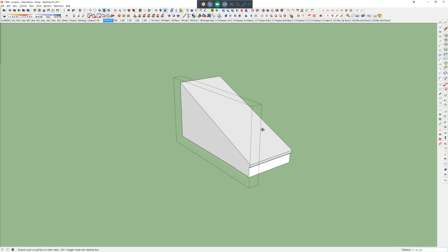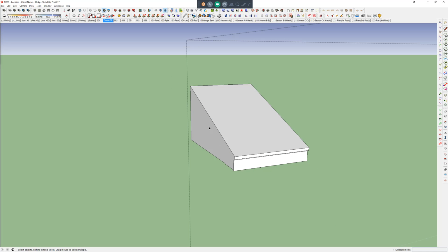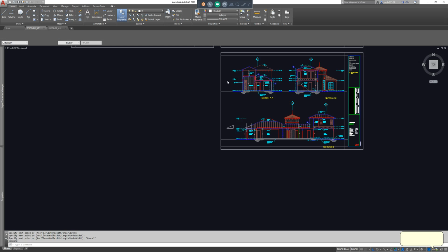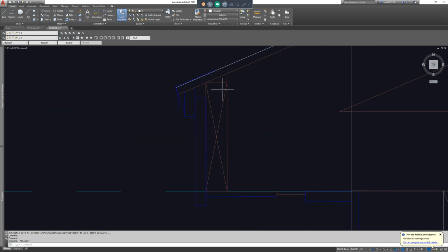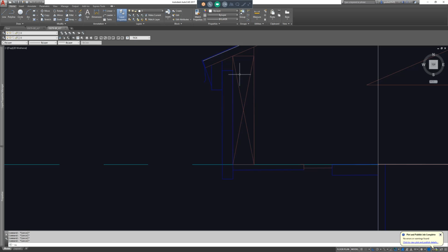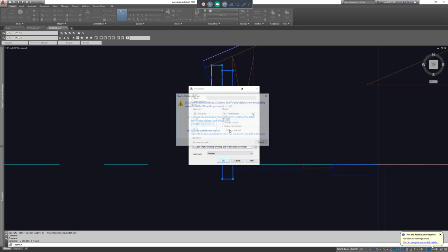I'm going to push-pull this just so I have a solid gable end to deal with. It's just a little easier. And coming back here, going back to the same place that I pulled everything from, what I really want to deal with is this board and this board. And I'm going to W block these out.